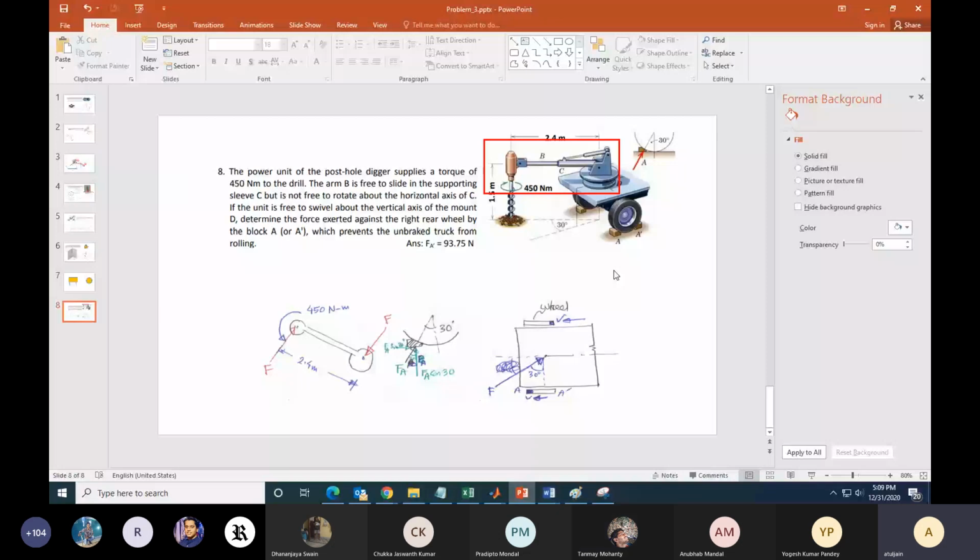Yes, sir. So the total reaction is F sin 30 equal to 2 FA sin 30. That is the equation that I had to use. F sin 30 is equal to 2 into FA prime sin 30. So how can the reaction at A be in the direction you have shown? It is going to be perpendicular to this wooden block.